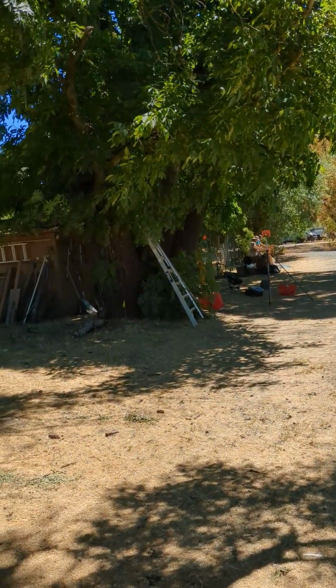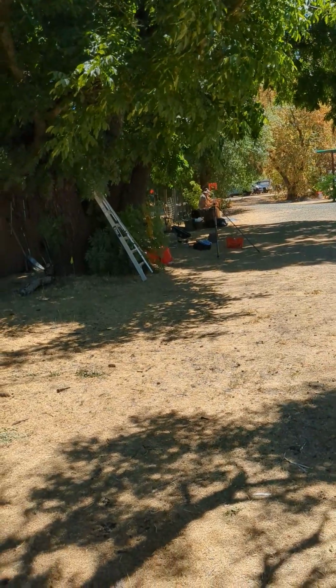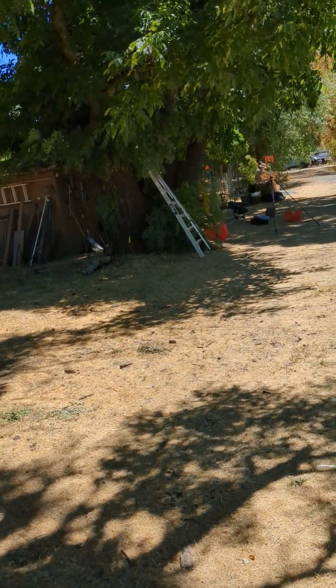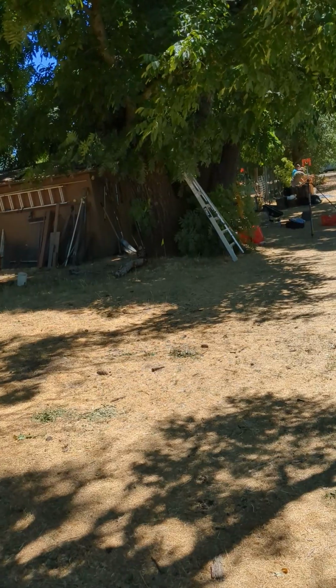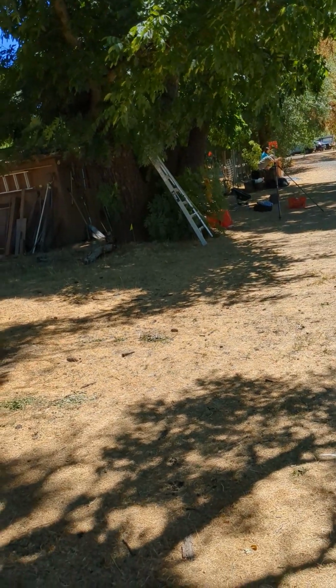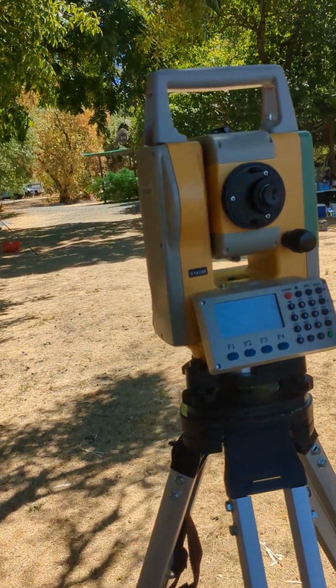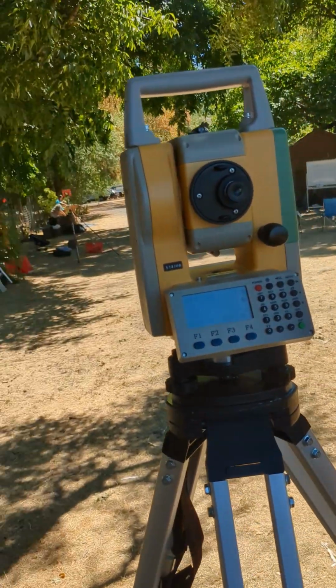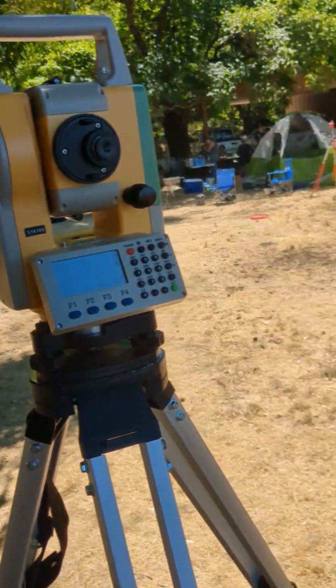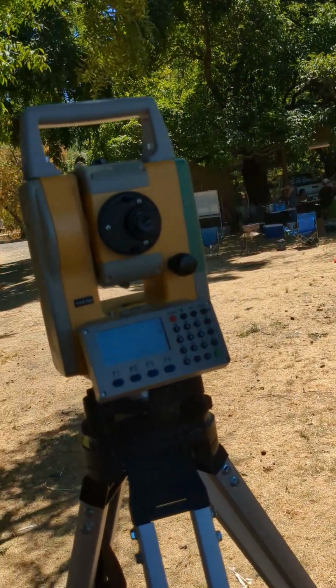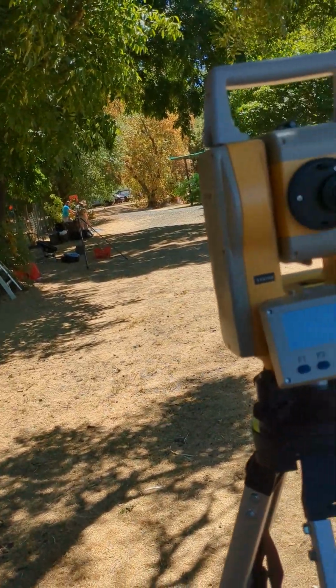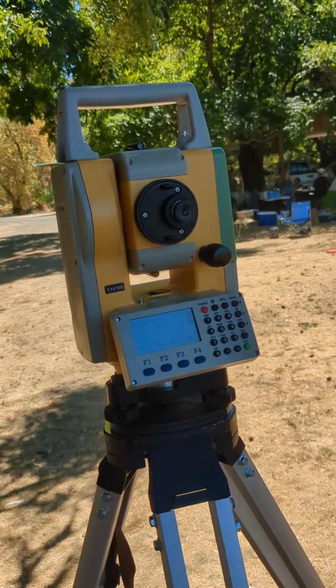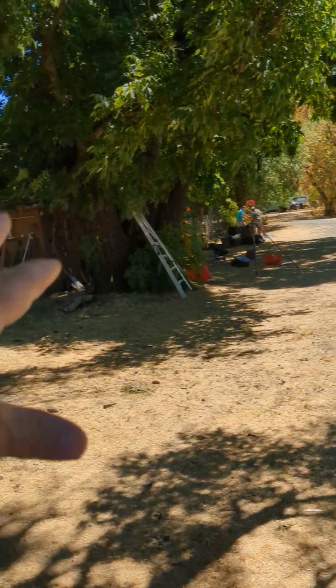From your datum, you might shoot to that GPS spot and find out the northern and eastern numbers from that and height, and you basically subtract those off. Remember that you have to also back off the 5,000 that you artificially put in there as well. So subtract 5,000 from each number, the northern, eastern, and vertical,